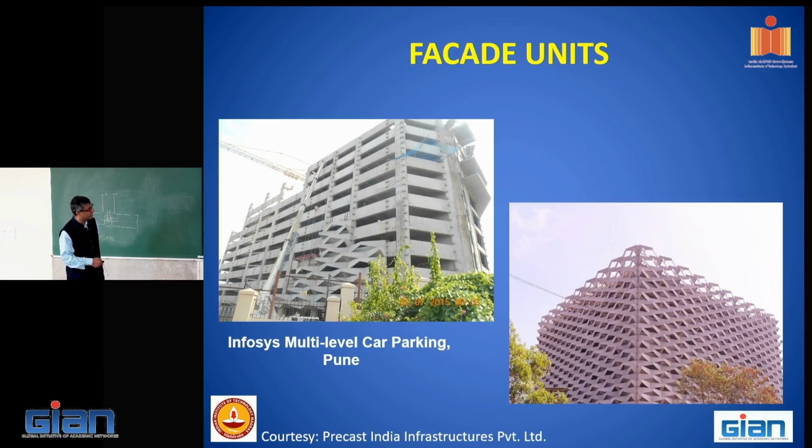This particular building, the Infosys multi-level car parking in Pune, if you visit Pune, I would say is a must-see building for a student of precast concrete. I was fortunate to go to the factory. It is made up of spandrel elements, columns, and then they keep some brackets. Over the brackets, they make this honeycomb type of facade elements.